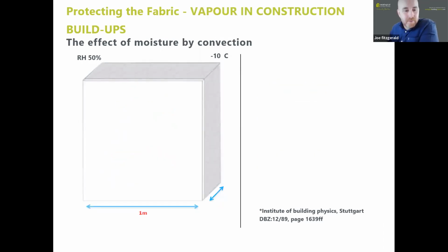But likewise, from a point of view of controlling the internal moisture, it's hugely important also. The plaster on the outside of the building can deal with the rain, but from the inside, the moisture generation that's coming from the inside, we have to control that at source, which is why it's called a vapor control layer. So under normal conditions, or under ideal conditions, that vapor can move only really slowly. It'll move by a process known as diffusion, where the tiny little particles move through the plastic at a really defined rate, and it'll be very, very slow and insignificant.